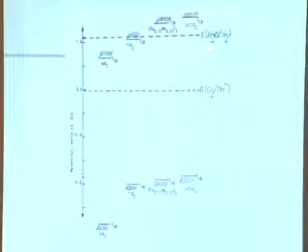Very underutilized. It's not really good in the sense that on the Earth, we don't have a lot of photons that are that big, and you notice you're throwing away an awful lot of that energy. But it does straddle the band edges. So if we happen to live on, say, the moon, this wouldn't be such a bad material. We got more UV photons coming out. The band gap here is about 3.5 electron volts, a little less than that, 3.2 actually.